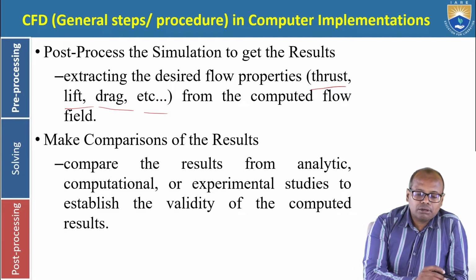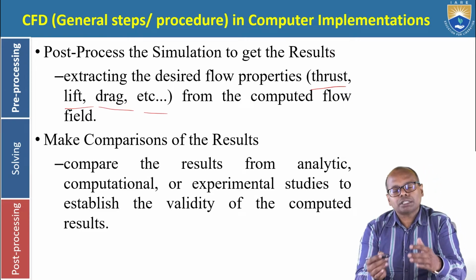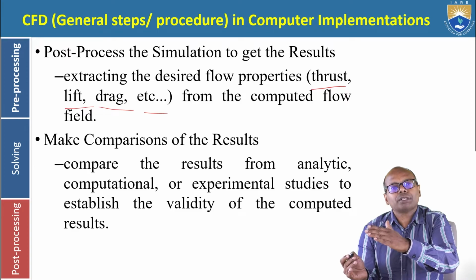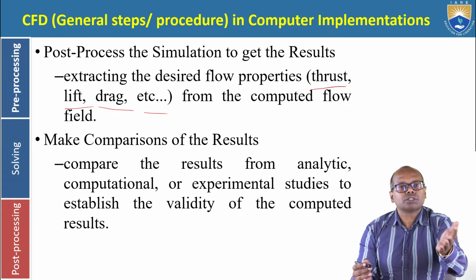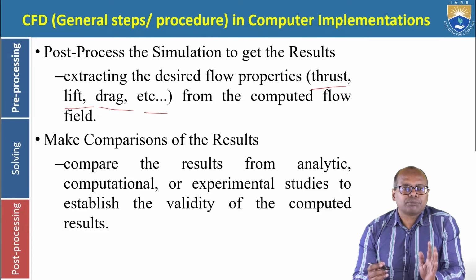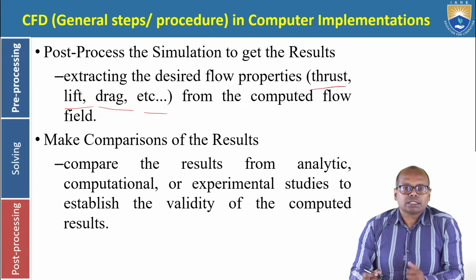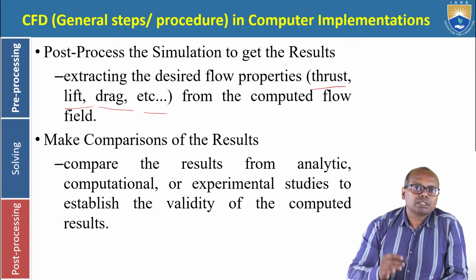Now I have to make a comparison of these computational results with some experimental results or previously done CFD results, which are already authorized CFD results. Then I can say that my computational values are accepted. This is called validation. So the validation should be done. Then only I can say that my results are correct.